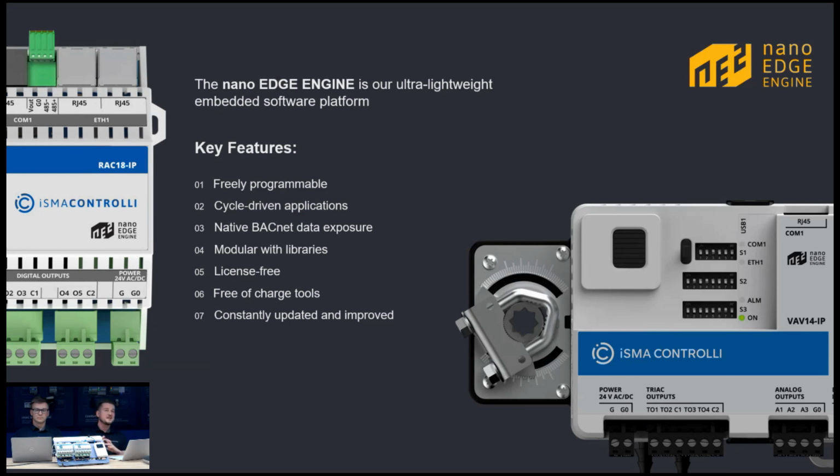So let's look at some key features of the Nano Edge engine itself that are shared throughout our controllers. First of all, it's fully programmable, and it's based on cycle-driven applications. That means you can create applications using logic blocks and a wiresheet, and you can drive not only one, but multiple applications in time cycles.